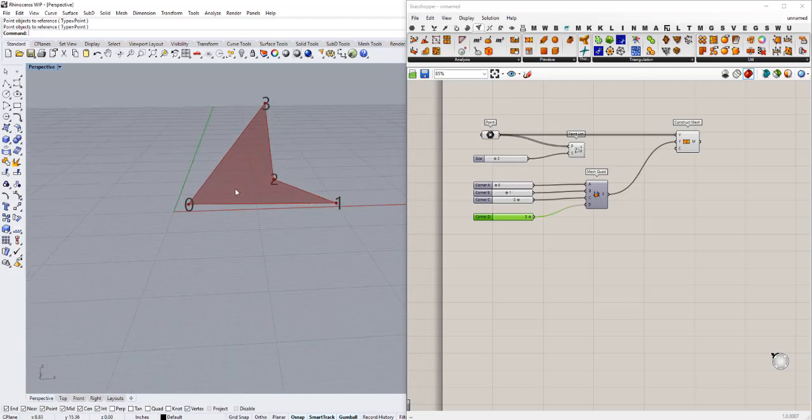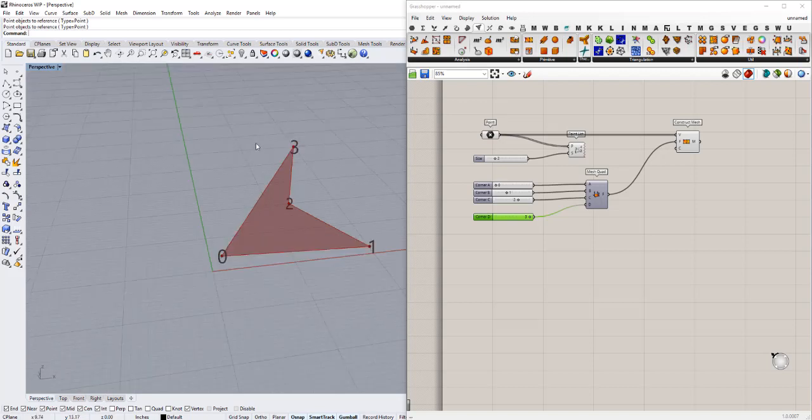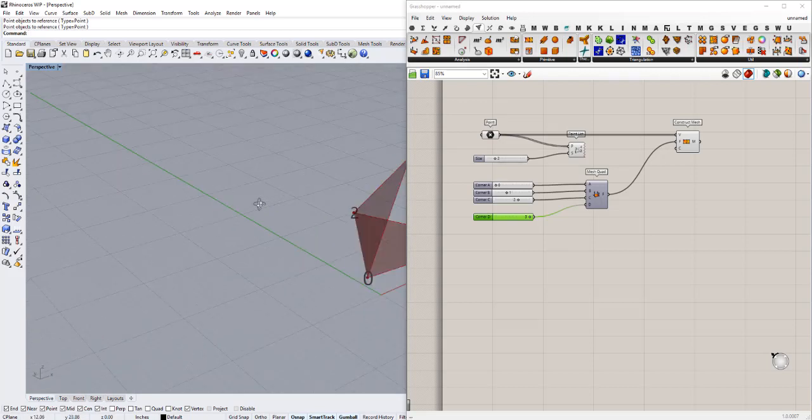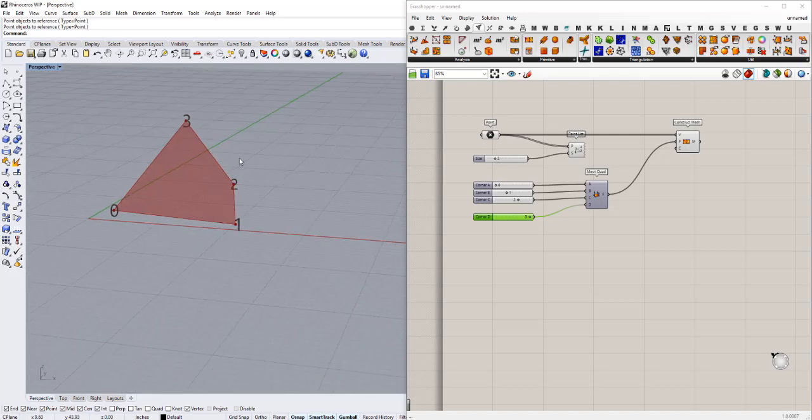that's definitely not a planar surface or a planar mesh. It's sort of bending around this little lower edge. So it's important to note triangles are always planar. So a triangular mesh, all the faces are going to be planar polygons. In most cases, quad meshes will not be planar. There are special cases that are planar quad meshes that can be made. That's usually more regular geometry, like a sphere or some revolved solid that can be broken up into a planar mesh automatically.